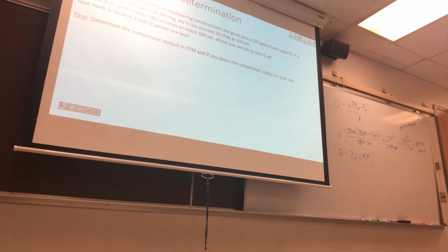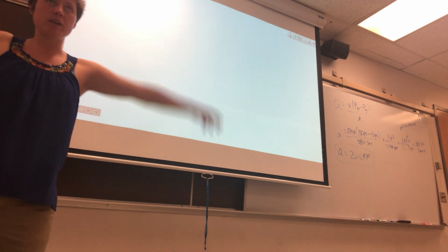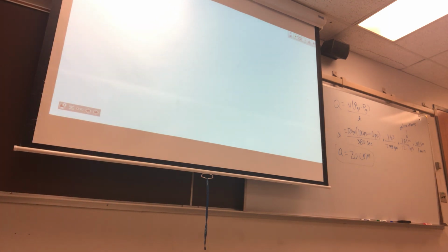Okay, cool. We've got compressors. We also have line losses. So what does this mean to you all when you hear line loss? Losing pressure over distance. Losing pressure over distance through the line that's too small. Yes, exactly. So you're losing pressure in your line because it's really long, due to friction. So there's a quick and dirty equation that we can use. It's actually pretty good, which we will use for estimating our line losses.